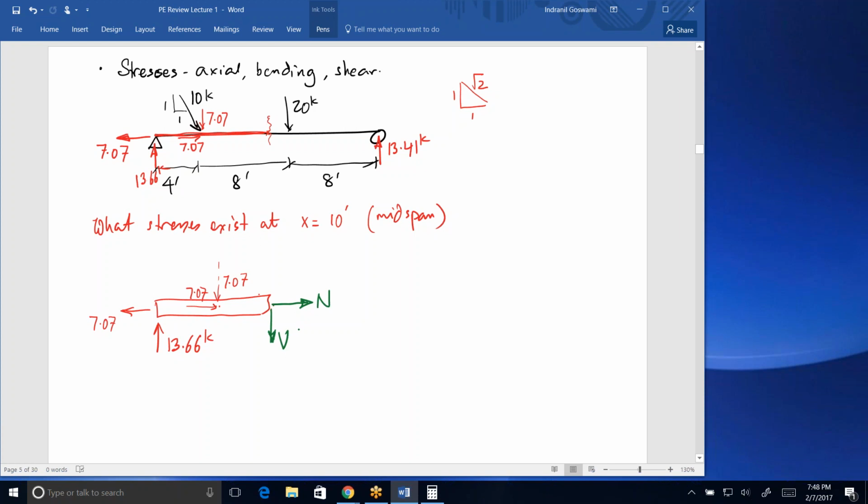So the adopted sign convention that is most common. Not that you could not go against the grain. You could do something different. But what you'll see in most places is tension positive, which we have encountered elsewhere. Shear, this is considered positive shear. Any kind of shear that pushes the left side up and the right side down. And consistent with that, this is considered positive moment, what acts like that on a portion of the beam. So the three unknown internal loads, not forces because one of them is a moment, the internal loads at that cut section will be represented like this.